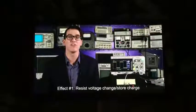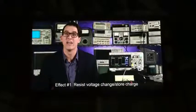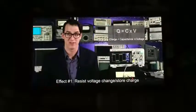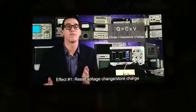We have the wavegen from my oscilloscope running through a resistor, and that's probed with channel 1, and then we're going to put a capacitor in parallel with that resistor to see what happens. The first effect that capacitance has on a system is it's going to resist a change in voltage and store charge, according to the formula Q equals C times V. So let's add the capacitor and compare before and after.